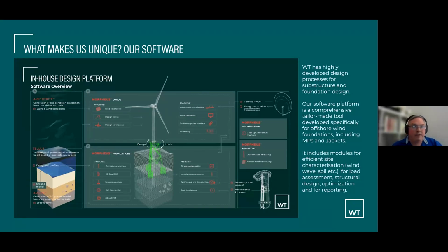So we have geotech data for every point, and we have water depth data for every single point. And we're able to gather that by taking the borings and CPTs at, say, 10 or 15% of the locations and translating that data to the balance of the locations through the geophysical analysis that tells us where the soil depths are. And the idea of the picture there is it shows you the different soil levels and what's in there.